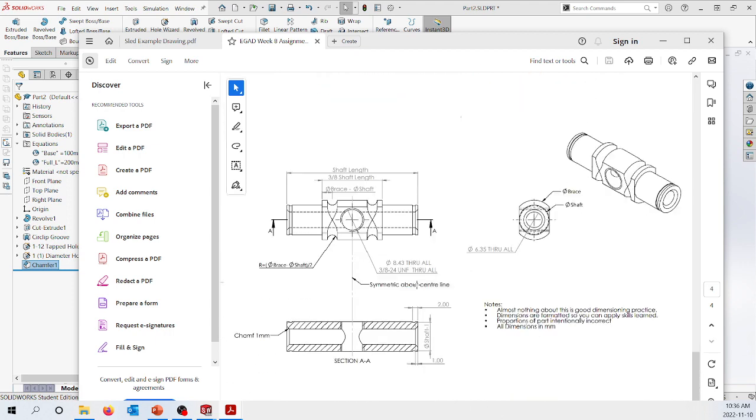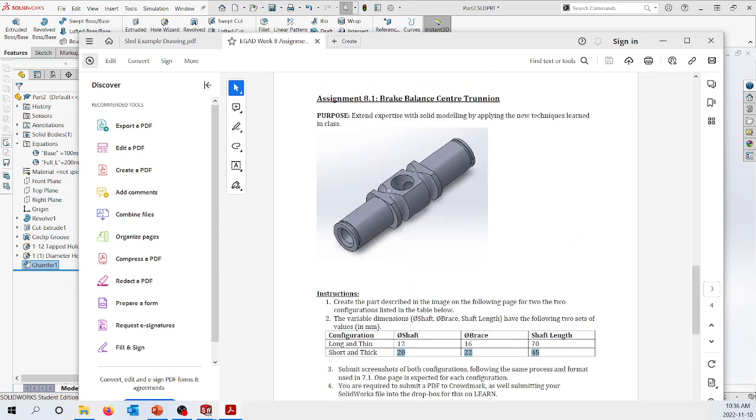A little heads up, this little weird wobbly feature here on this part looks difficult and complicated, like you don't know how to model it. A hint, you don't have to. SolidWorks is going to do that work for you. Think about order of operations and the sort of things that we've done in this class. That is a side effect of other operations. You're not directly modeling this wobble thing. That is a side effect of interacting and intersecting geometry.